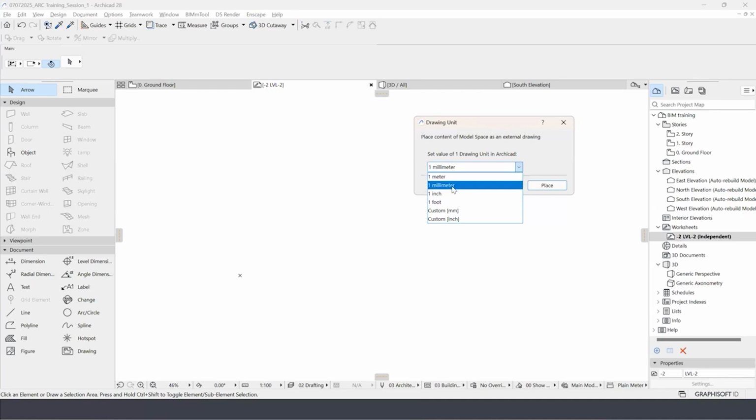One of the reasons is that in most cases when we do a scale, let's say your model has been imported with a millimeter precision or metric precision, and when you scale it, even if it has a small amount of error, that error is going to be multiplied, and that is not an ideal way of working. So that's why I'm saying go and find out which unit you worked on and then bring it into ArchiCAD.